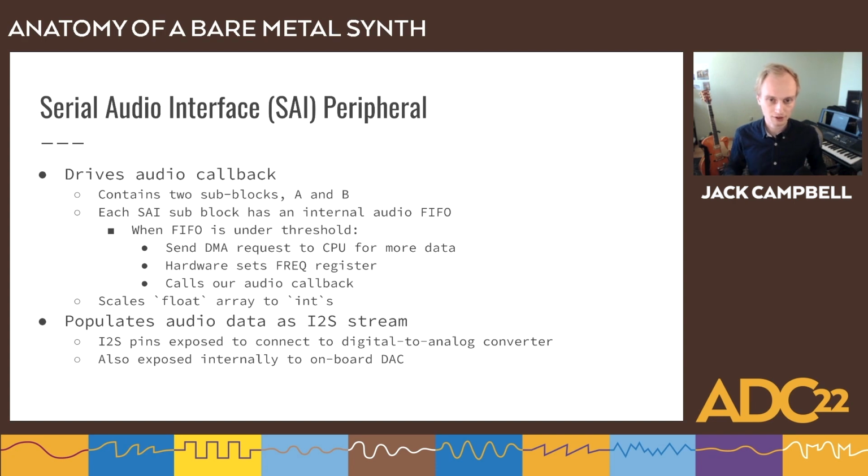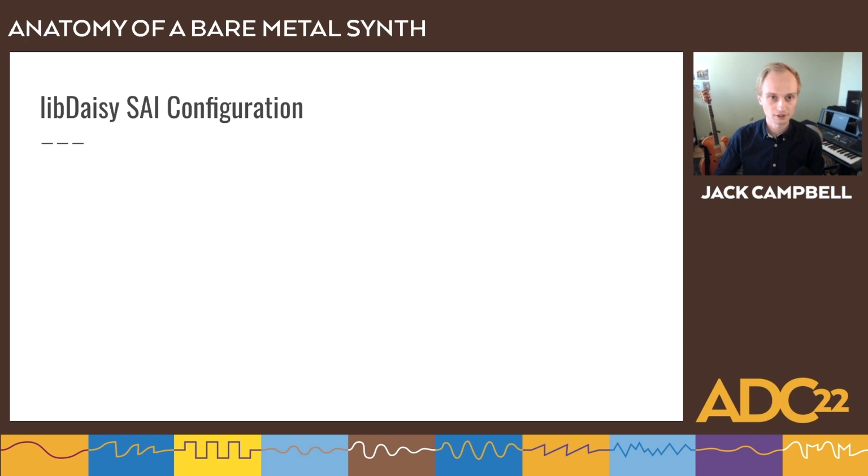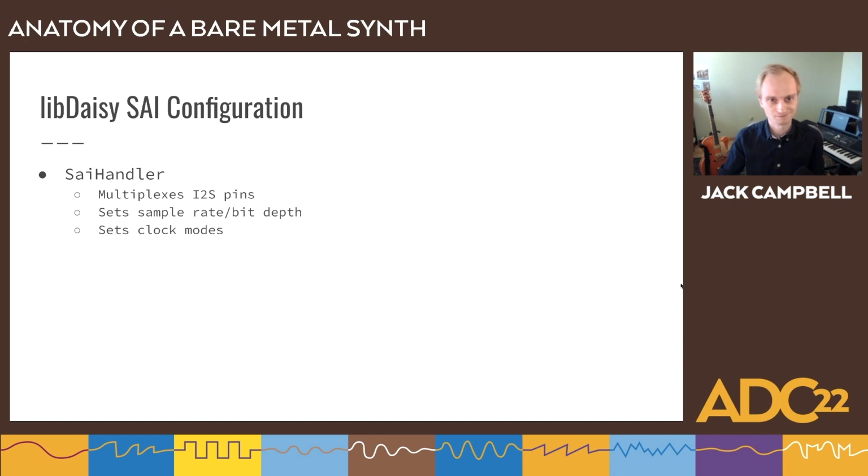In order to get that analog audio out using the onboard codec, there are internal connections from the microcontroller to the audio codec, sending that digital audio data and converting it. Or you can actually get the digital signal out on a series of pins, and we'll talk about that after this slide. I just want to show, if you're spelunking into the code, I don't want to dwell here too long,